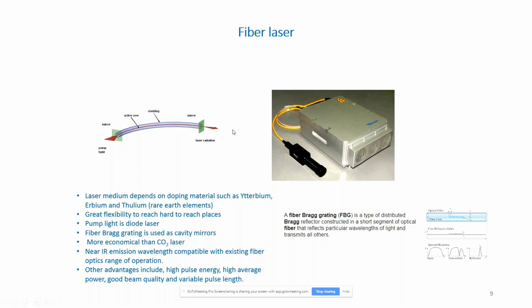So these fibers have great flexibility to reach hard to reach places. The pumping is through diode laser, and they're more economical than CO2 lasers. And basically, they have a lot of advantages such as high pulse energy, high average power, good beam quality, and variable pulse length.